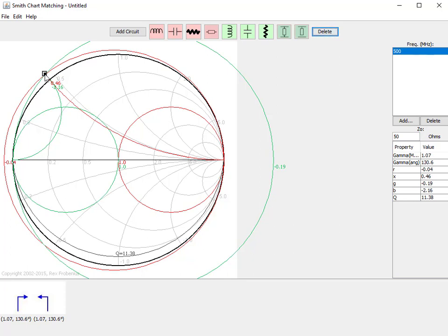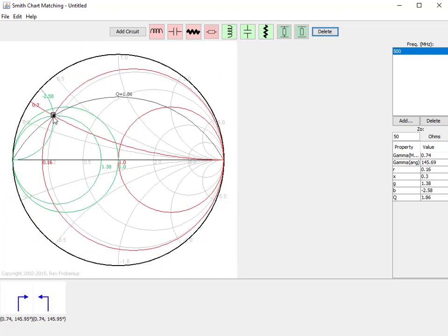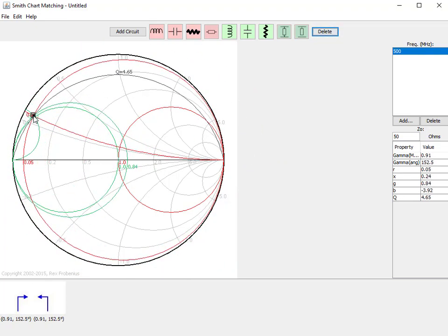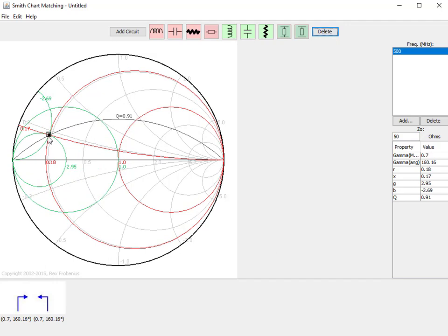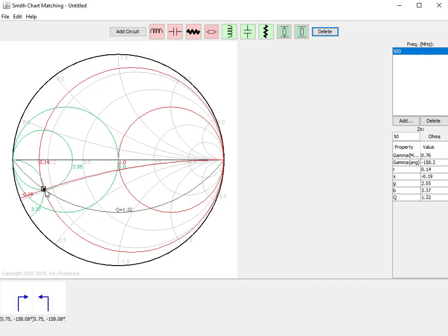And those are going to be based on measurements of the transistor itself. S-parameter measurements of the transistor will let you predict regions of stability on the Smith chart, where if you provide the transistor with the wrong termination at one end or the other, it's going to oscillate. And that can be predicted on the Smith chart graphically using S parameters.